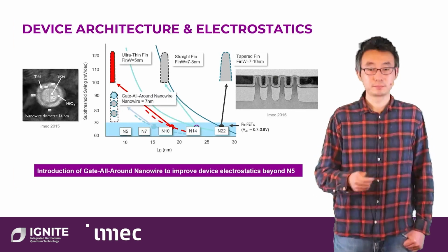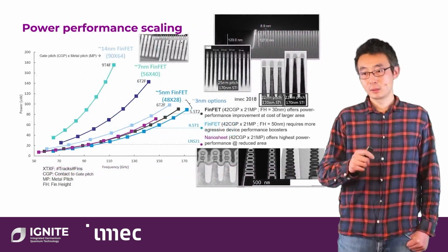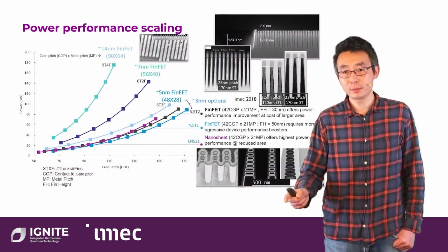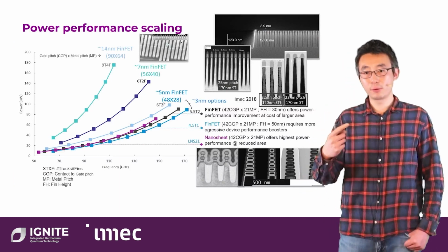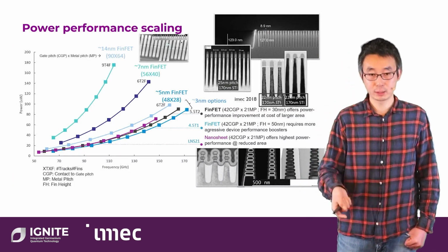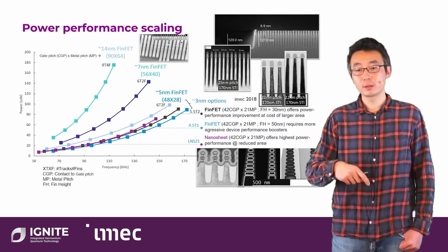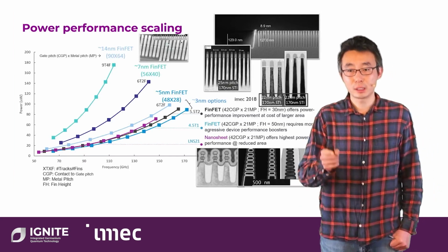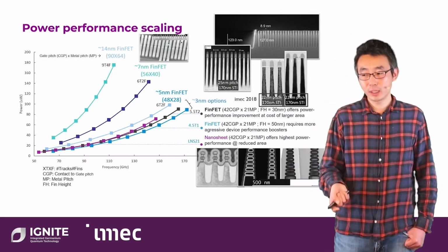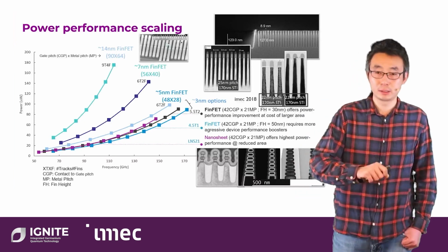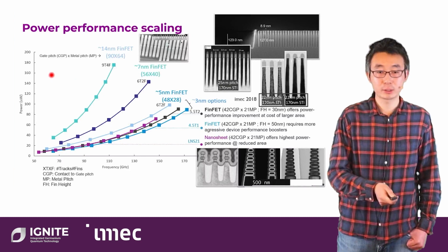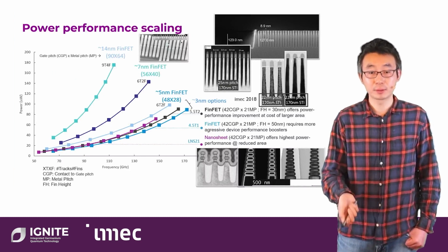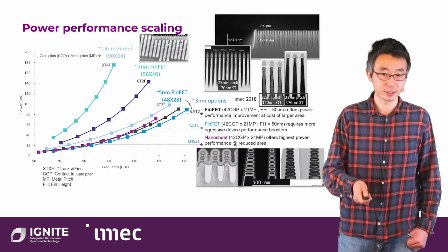And when we are talking about those 7 nanometer, 5 nanometer, or 14 nanometer, those things actually follow the original prediction of Moore's law. But because of the introduction of the fin and also the nanowire, those numbers may not actually be correlated to the device geometry. So the real interesting parameter is actually to look into the gate pitch times the metal pitch. Those are the things that matter.